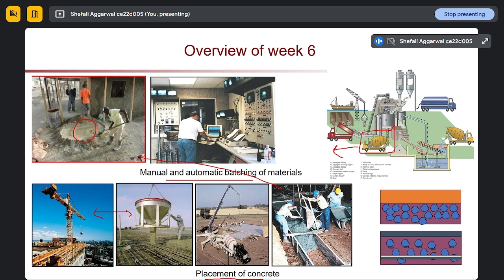So if we talk about how cement is generally produced, we take limestone from the limestone quarry. Limestone is collected, and then it is broken down into small particles. We are grinding the limestone into very minute particles, and then we are adding our slag and sand to it, grinding it, and after grinding, we will be heating it in the kiln.